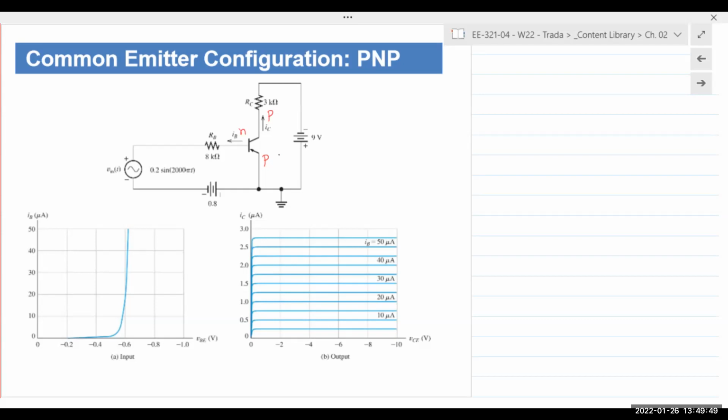So just wanted to explain that. Students typically do have questions about that. Why do we have negative numbers, even though it's a forward bias diode? Well, that's the reason. It's just that our reference point is the emitter when we actually plot it here. That's all. But it's still a forward bias diode, and the collector junction is still reverse bias.